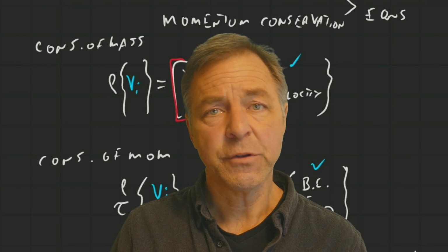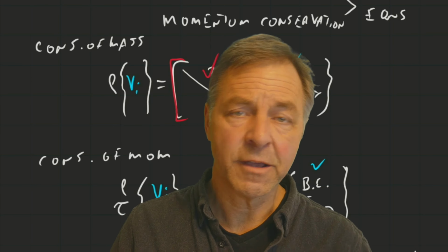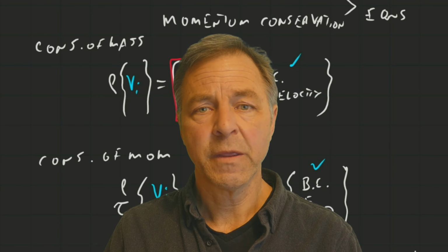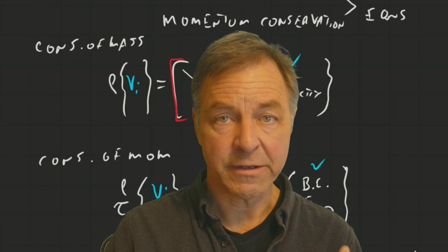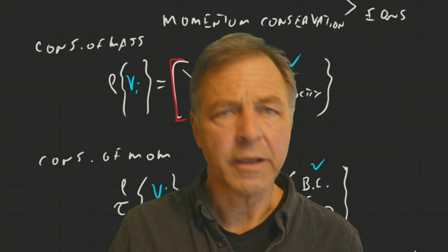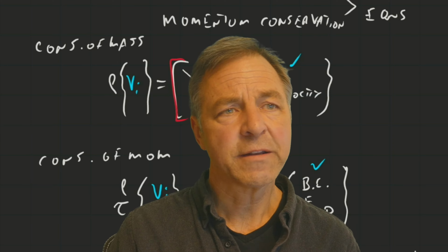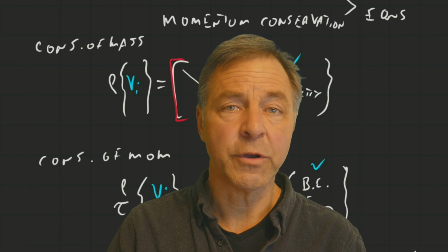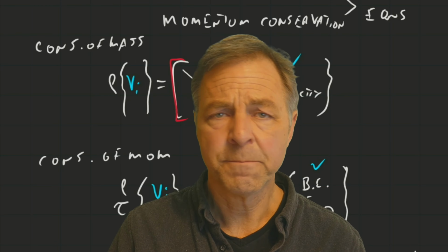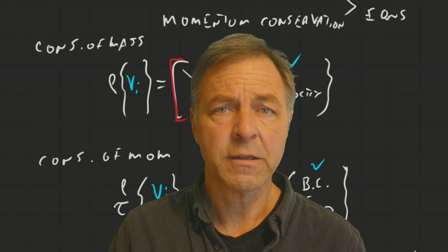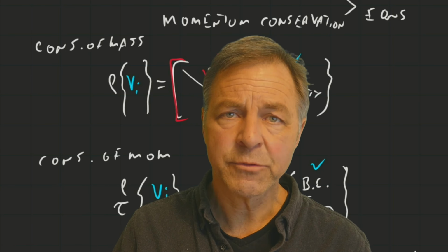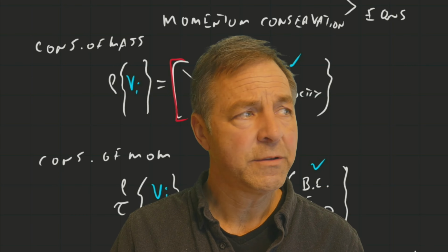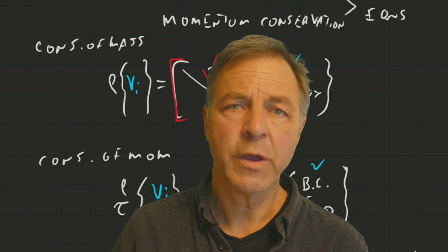And certainly if you probed more deeply, as I did not on camera, at the plots of the different velocity fields at different angles of attack, they look kind of cool. They look realistic. In fact, you can predict the point of separation on the backside of the airfoil. That's sort of consistent with the real data, but when it comes down to looking at the actual numbers of forces, they don't match the real world very well.